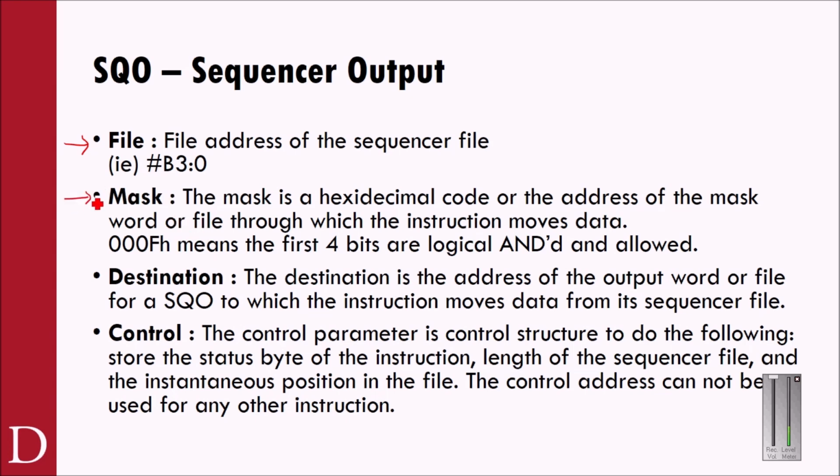And then I have a mask, and the mask is a hexadecimal code. If you want the mask to do nothing, then I would address the mask as FFFF H, standing for hexadecimal. And what that means is each one of these F is a hexadecimal corresponding to 4 ones. And so there's 4 ones, 4 ones, 4 ones, 4 ones. So it doesn't matter what sequence of 16 bits I'm going to mask with this, or I'm going to AND with this, they're all going to pass through. It's kind of like when we do some of the stuff with the subnet mask with IP addresses and things.